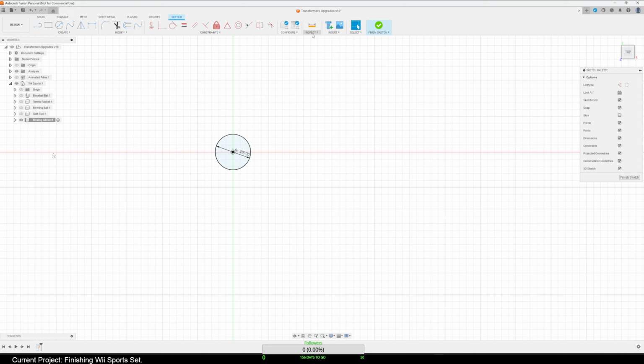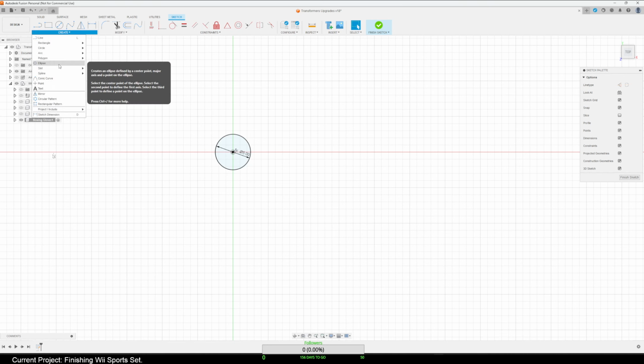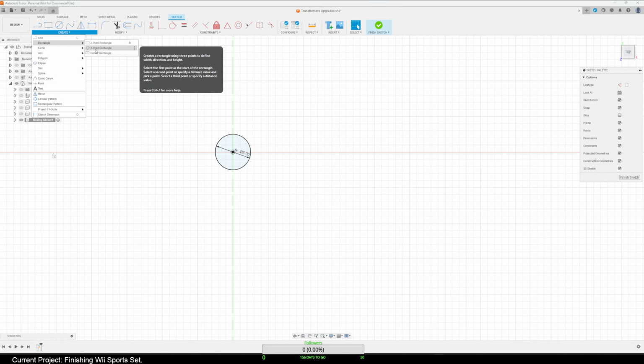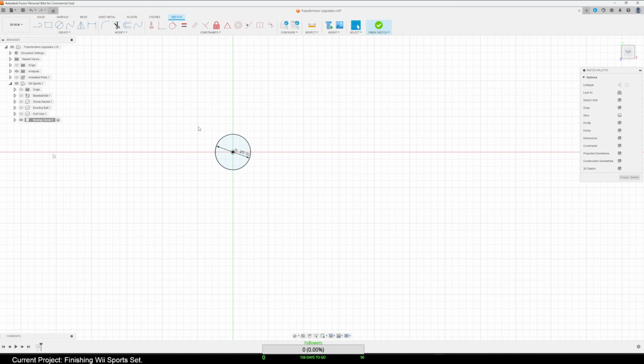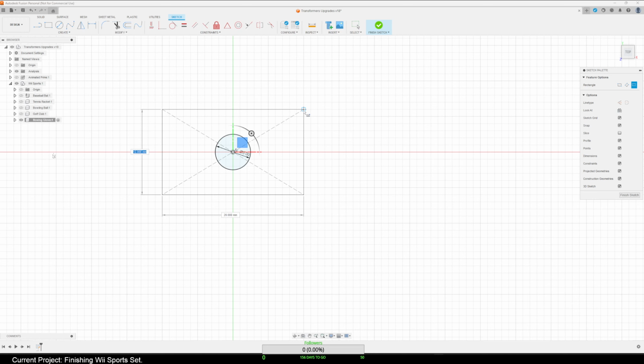All right. Here's how we're going to do this. The whole hand is 16 and the peg is 5. That means there's an 11 difference. That doesn't really matter because I'm going to make a center rectangle. Did I just hit 3-point? Oh, I must have done circle. Oh, no. Okay, there we go. You can do weird math, but then I just forgot I can make a center rectangle. 16.